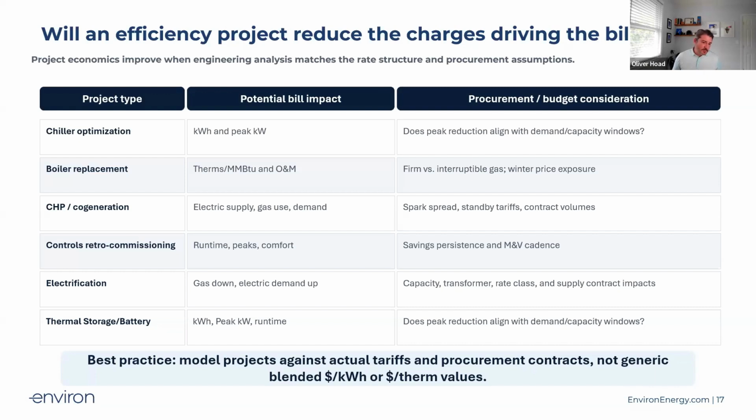With a boiler replacement, if you're at a single fuel source boiler and you can implement a project with a dual fuel source, you could actually look at shifting your rate class, your service class, from firm to interruptible, which can have a substantial decrease in the overall cost. So make sure all these things are considered when you're modeling out the project.